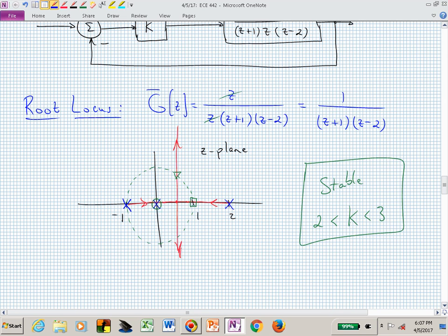But now we have, do you see now how to create this root locus? This structure of a root locus you should be able to do in your sleep now. When you have two poles and effectively nothing else, what's going to happen? They're going to come together, they're going to meet halfway between each other, and then they're going to go off at plus and minus 90 degrees. And now you could compute, without doing anything real fancy, the average of those two locations, and that's where they break away. Question?